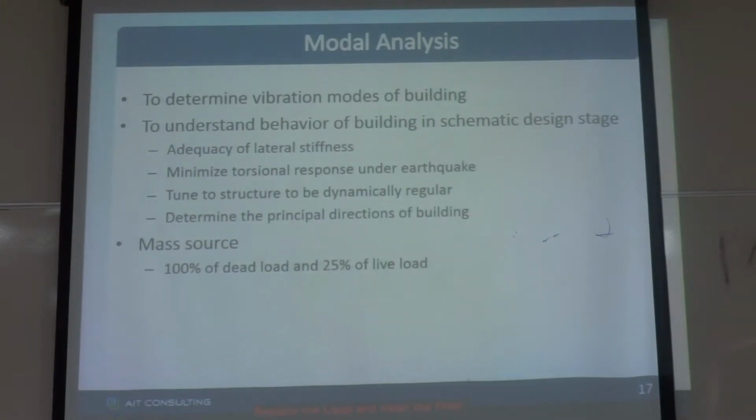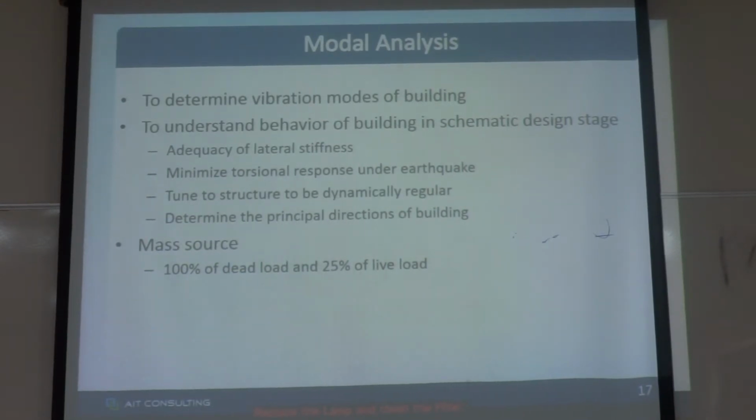Okay, this is the modal analysis. In modal analysis, we check the vibration modes, and we can check the adequacy of lateral stiffness and torsional response. Then we can tune the structure to be dynamically regular, and also we can determine the principal directions of the building. I will explain how the principal directions of the building can be determined.